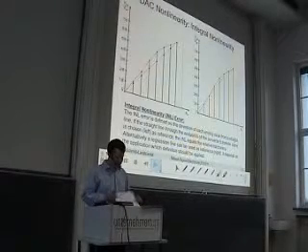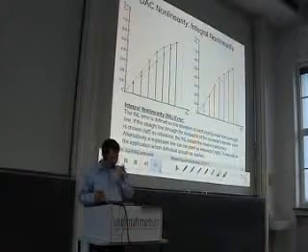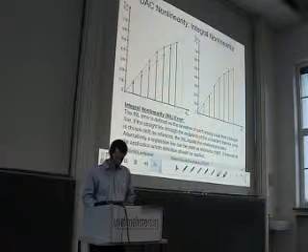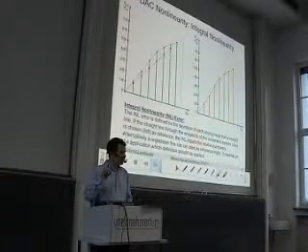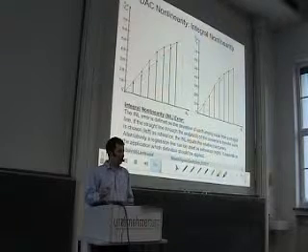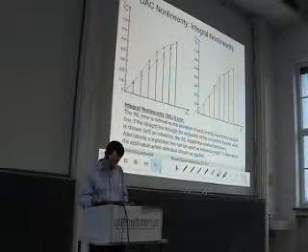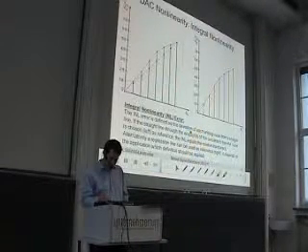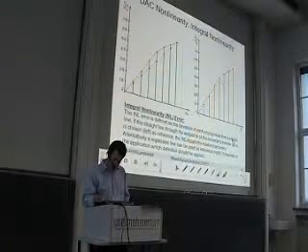A quantity that is more common in literature is the so-called integral nonlinearity. The integral nonlinearity is defined as the deviation of the actual curve from a linear line. Somewhere I wrote this: the integral nonlinearity error is defined as the deviation of each analog value from a straight line.